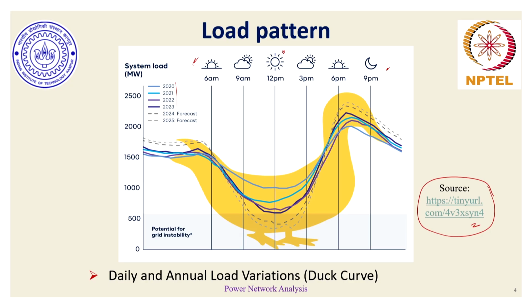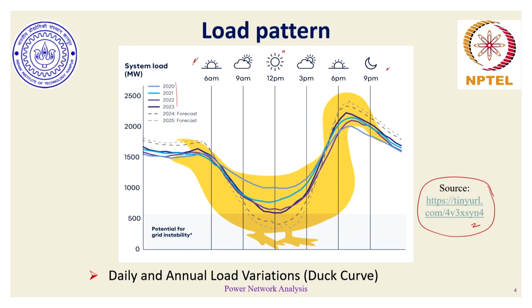And again, as evening sets in, lighting load tends to go up, people return to their homes or cottages, wherever they stay, and in the evening we need light, so the load again tends to go up. And post dinner, usually people tend to sleep, so around 8 or 9 p.m., the curve tends to go down, and again from 6 a.m. it tends to go up.